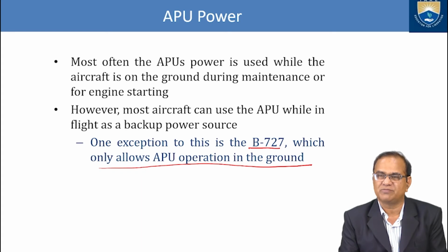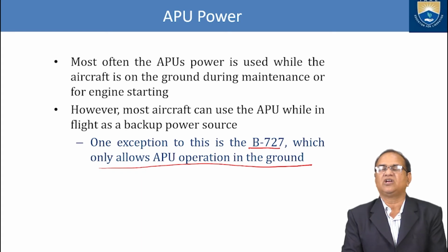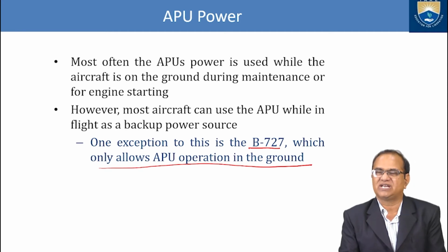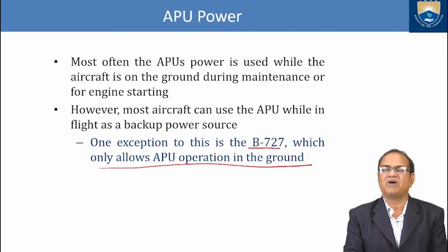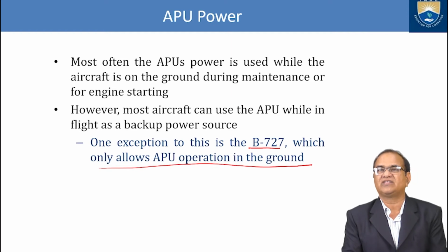Once we want to do some testing, some landing gear check, your hydraulic operation, pneumatic operation, or electrical power generation, or you want some navigation, communication, you want to test on the ground, every maintenance work has to be performed by the external power supply or by the auxiliary power unit. The main engines are not started for the maintenance purpose of the aircraft.